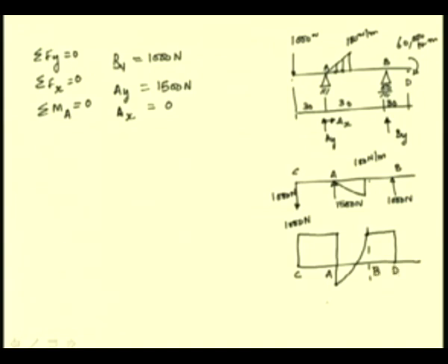On the beam. Now, from this shear force curve we can determine the area under this curve, and we can use the same to construct the bending moment diagram. So, at C we have a 0 bending moment.